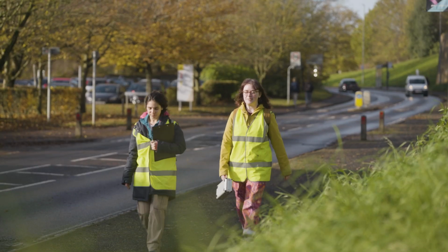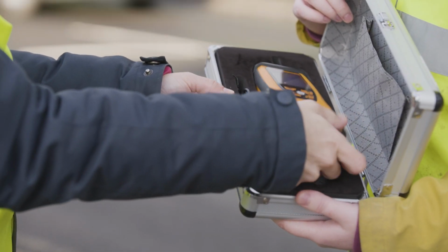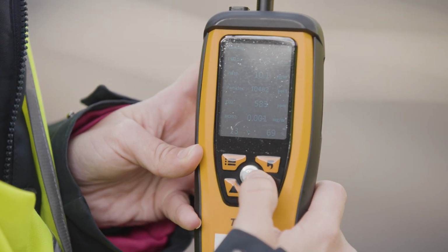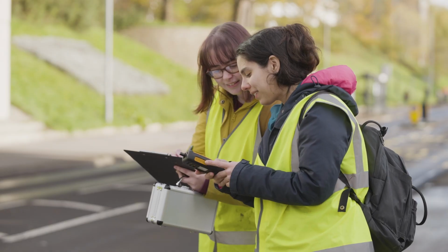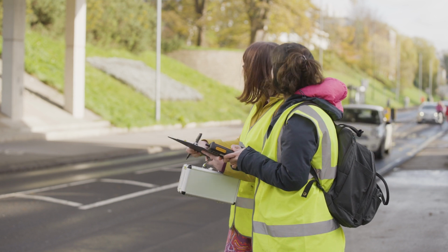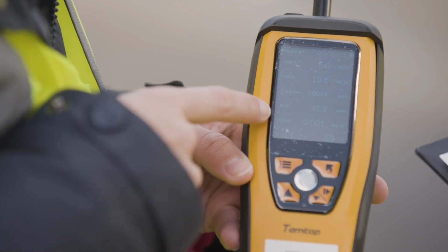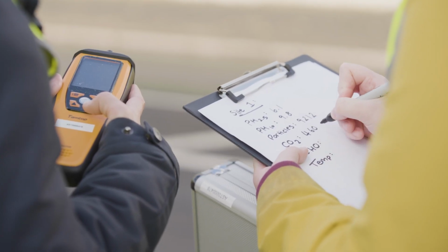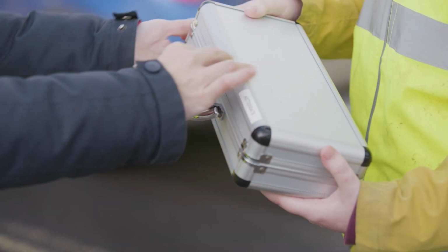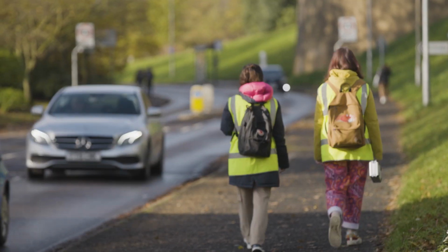You can use handheld meters, which provide instantaneous measurements of different air properties, including CO2 and PM10 concentrations. Remove the device from its case, turn it on, and check it is set to the correct parameters and units desired for your measurements. Before taking your readings, ensure you position the device in your sampling location. Once ready, record the readings displayed on the screen. Some devices may record this for you, and the data can be downloaded after returning from the field. Once finished, turn off the meter and store it securely for transport to other sampling locations.